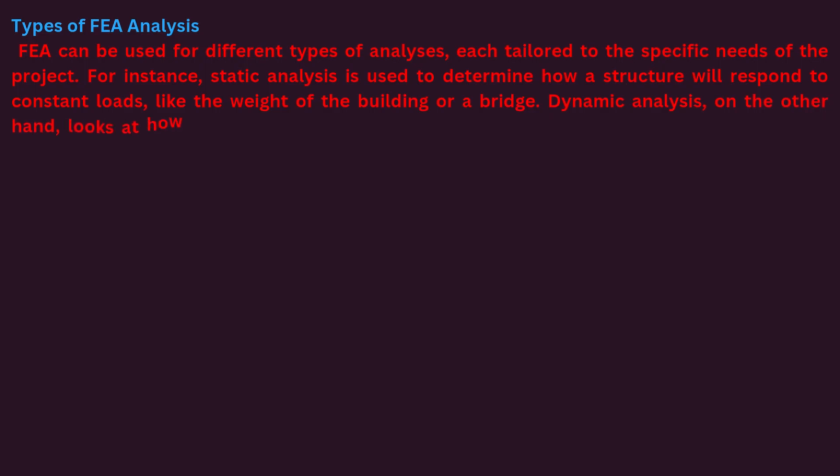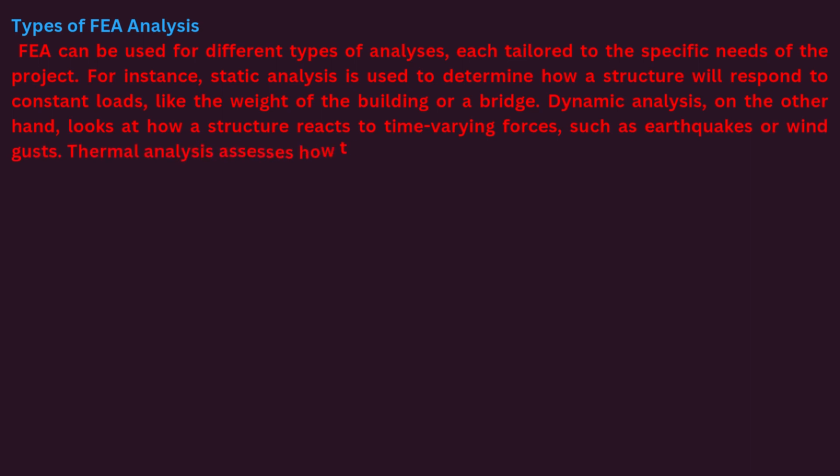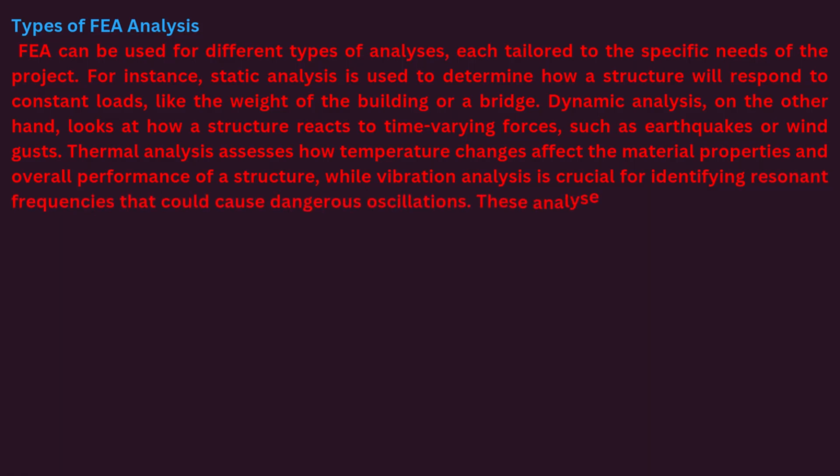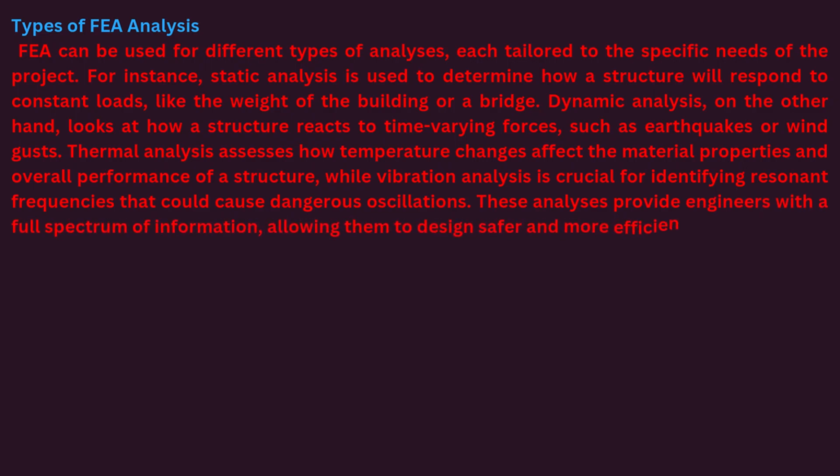Dynamic analysis, on the other hand, looks at how a structure reacts to time-varying forces, such as earthquakes or wind gusts. Thermal analysis assesses how temperature changes affect the material properties and overall performance of a structure, while vibration analysis is crucial for identifying resonant frequencies that could cause dangerous oscillations. These analyses provide engineers with a full spectrum of information, allowing them to design safer and more efficient structures.